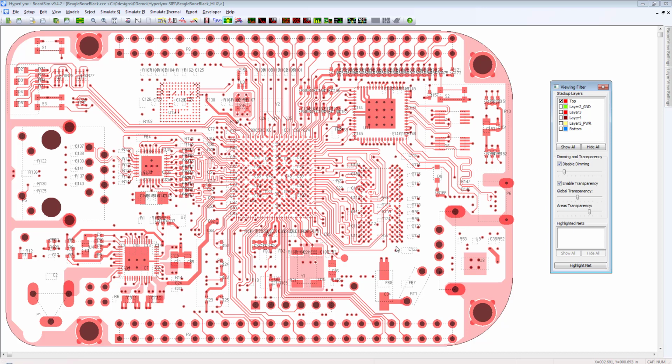Here in this area we see the DDR3 low power memory, and in my project I used Micron devices, and I also downloaded from the websites of the component makers the IBIS simulation models of the two parts.